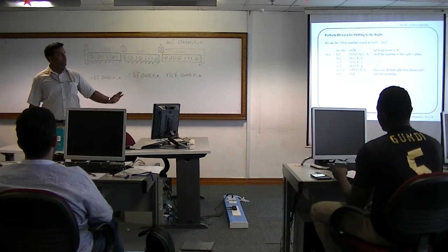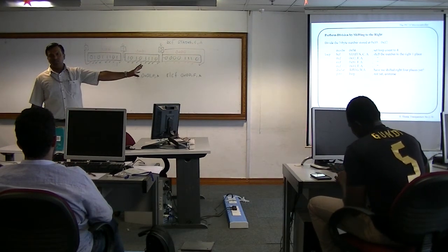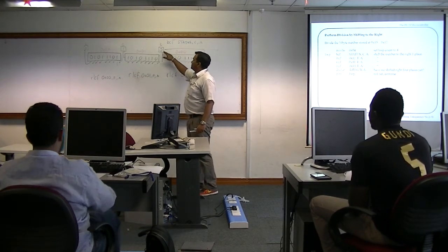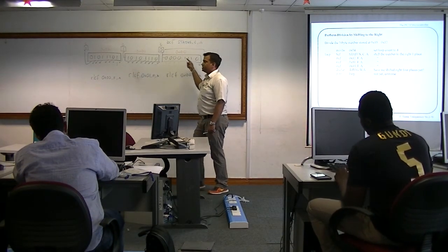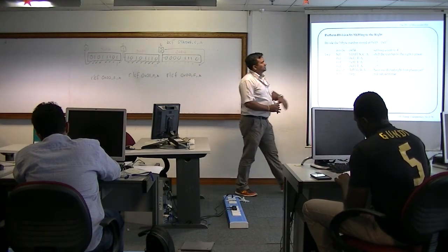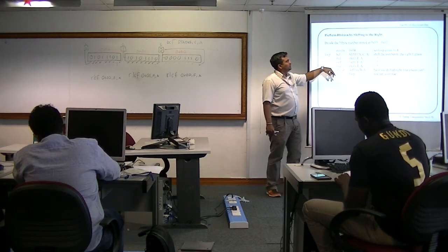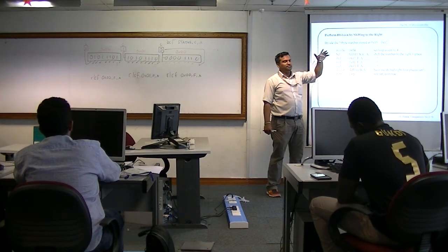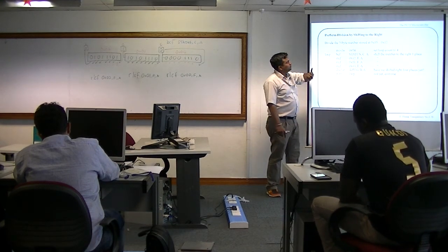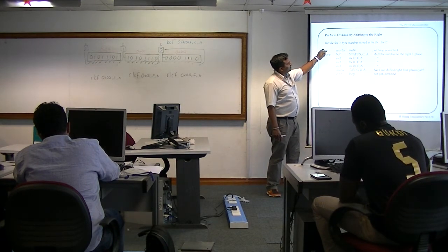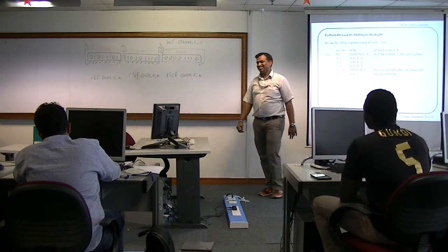The same thing also applies for division. Exact same thing. If for multiplication the 0 is entering this side, for division the 0 will be entering the other side. Anyhow, you must make sure that the status register carry is always 0. In this case, divide the 3-byte number stored at 10, 11, 12. Only 3 bytes. But it says divide by, suppose we divide by 16.